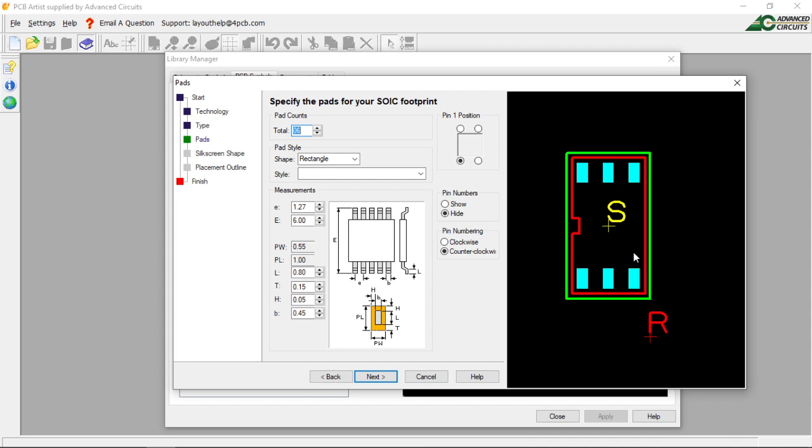And then we're going to need 2 pins for what? Well, for ground and power. So we've got 3 inputs, 1 output, and then we got the power. Now, the other thing we could do, which might even be better, is you usually like to put pins together that are like the power. So we could say 1, 2, 3 is the input, and then we could have the output here, and then we could have power and ground here. That might be worth considering, and that'll make it easier for the layout too. Have the power and ground here, then this out, and then these coming as the input.